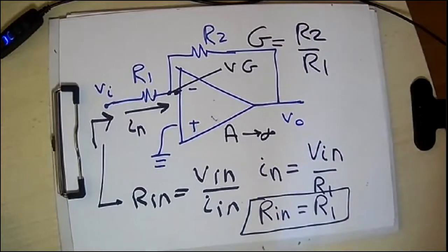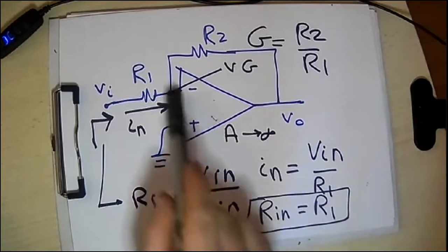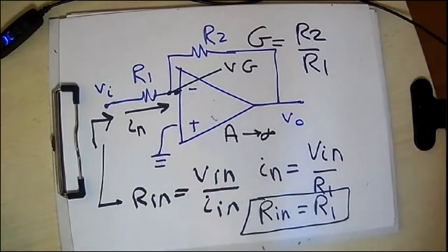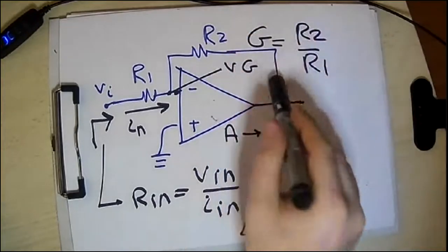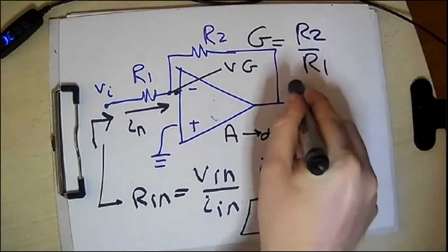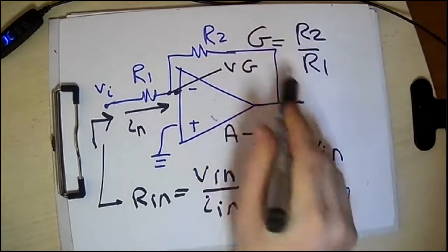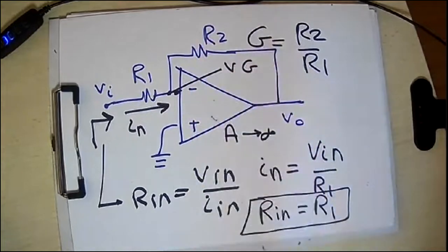So whenever you increase the resistance R1 in order to make this amplification stage ideal, this will automatically affect the gain, as you are lowering the gain. Whenever R1 increases, of course, gain will decrease. So this somehow limits your controllability, your tunability of the gain. If you remember, we said that the main advantage of the closed loop configuration is its tunable, controllable gain.